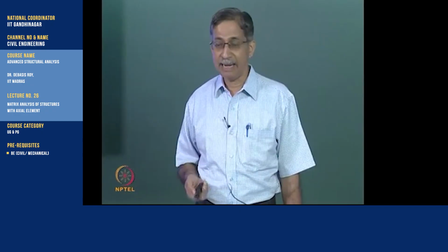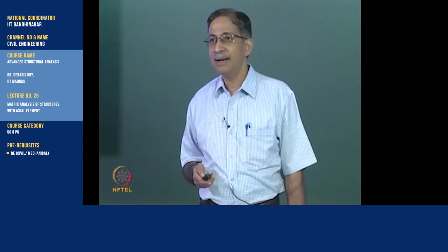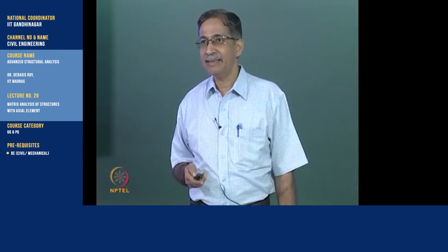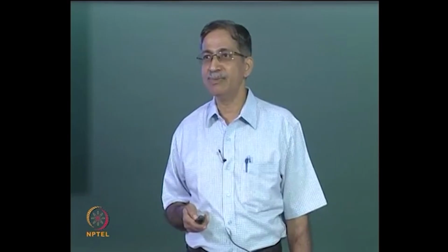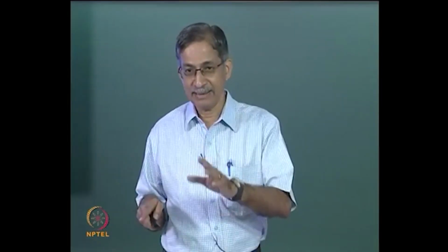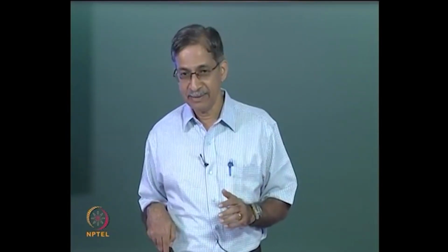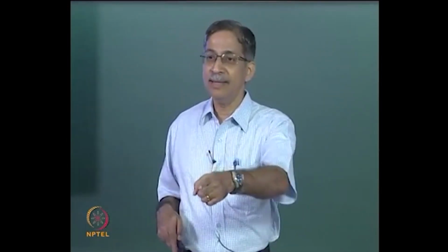Okay, so you also have support settlements here at the redundant coordinates. That is, you have D4 and D5 as minus 0.005 and minus 0.020. I would like you to think of what you need to do. I am not going to solve it here, but that is something for you to worry about. Supposing I had a rotational slip theta A equal to 0.001 radian. How would you deal with it? So please note down, that is a question you will get in your examination.